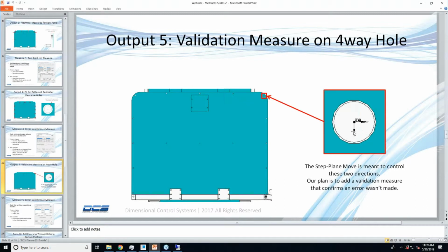Now, if these two directions aren't exactly right, or maybe I accidentally have my right-hand panel or left-hand panel in a move down the line and didn't realize that I had it as an additional move part, then that move would have been overwritten, and I could start to hunt down why this isn't doing what I think it's doing. This would be the first step that I do, just a sanity check to make sure that everything is lining up the way I think it should.